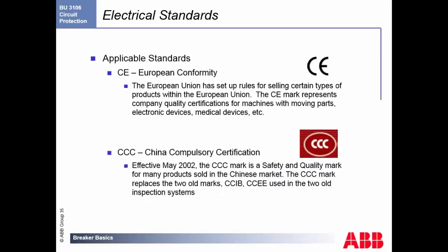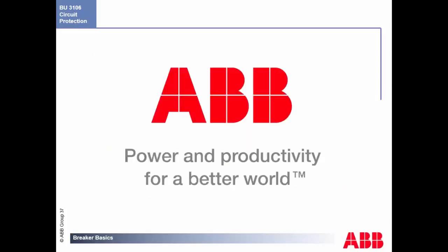Applicable standards, we're not just located here in the United States. Most of the industry is also complying with CE, which is the European UL, if you will. Triple C, which is the China UL, if you will. Most of the time, if you have UL, you're already cleared in all the North American markets. They do carry a CUL as well, which is for the Canadian market, and NOM, which is for the South American market.